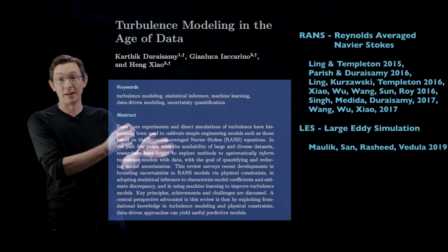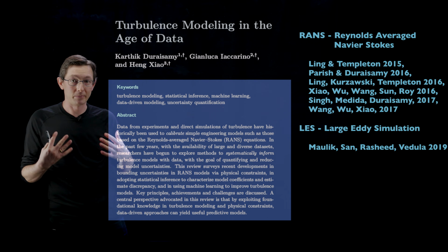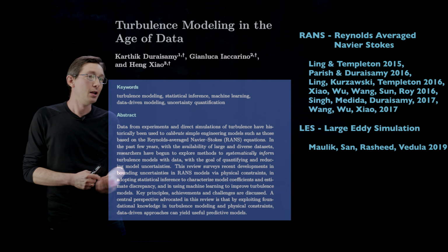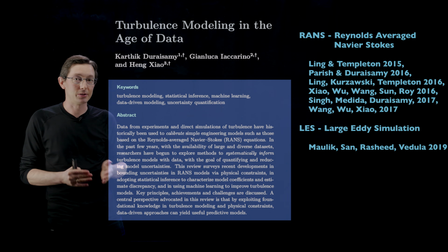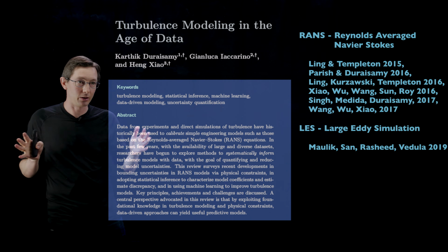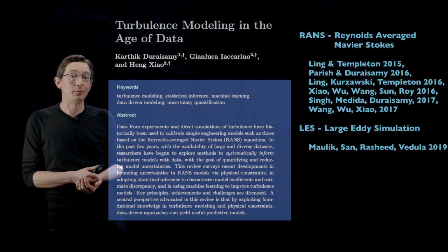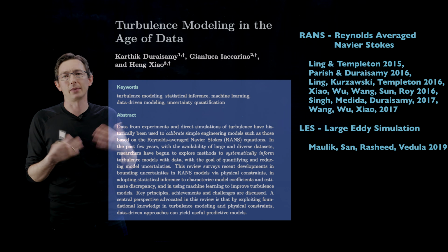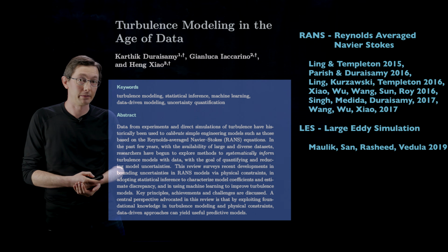This is the entry point. And on the right, I have some of my favorite research papers on this closure modeling problem. You have a lot that are dealing with Reynolds averaged Navier-Stokes equations, which is a time averaged equation. And then on the bottom, you're starting to see people apply this to large eddy simulations. Okay, and this is a tiny fraction of the wealth of good work on closure modeling.